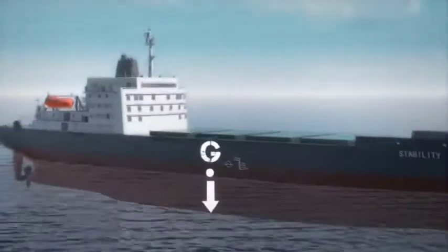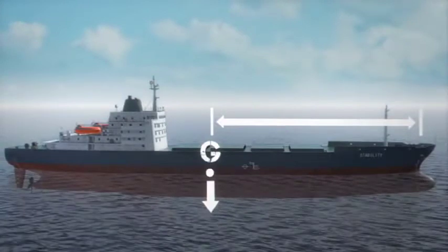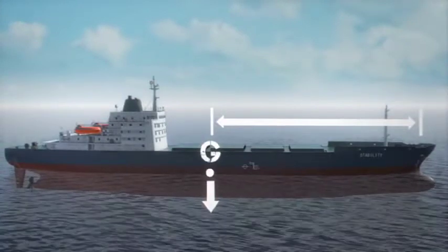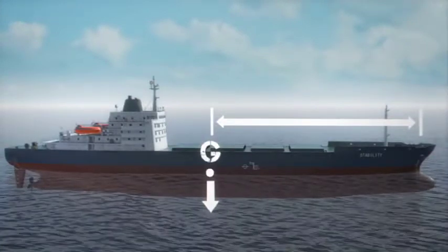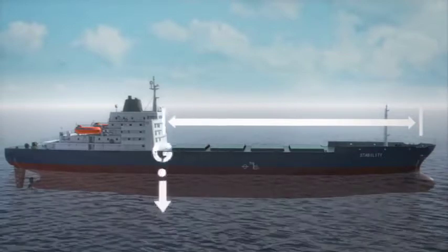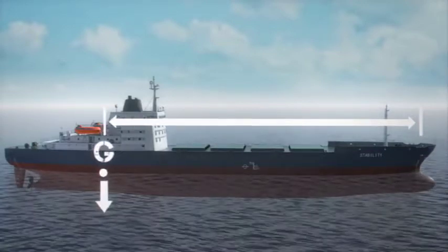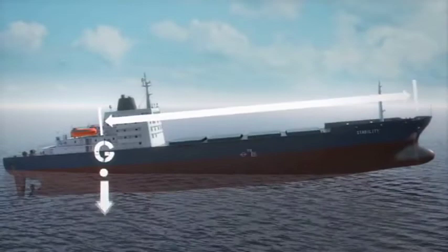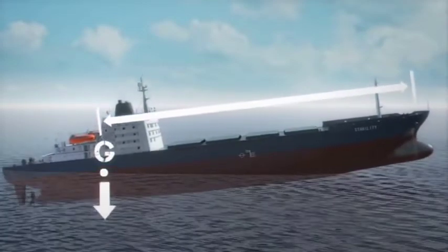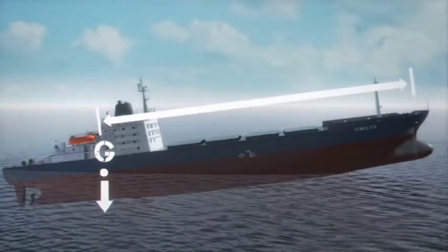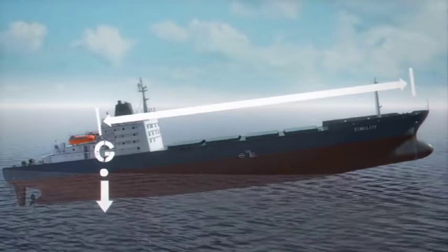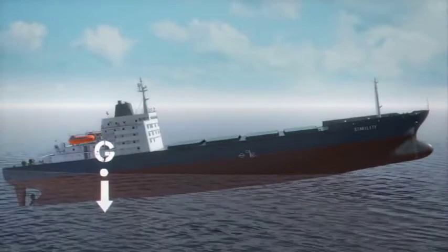A moment is nothing more than a force or weight multiplied by its distance from a particular point. Think of it as a lever. A moment can have a greater effect because the distance increases or because the force increases. In the imperial system, moments are measured in foot-tons.